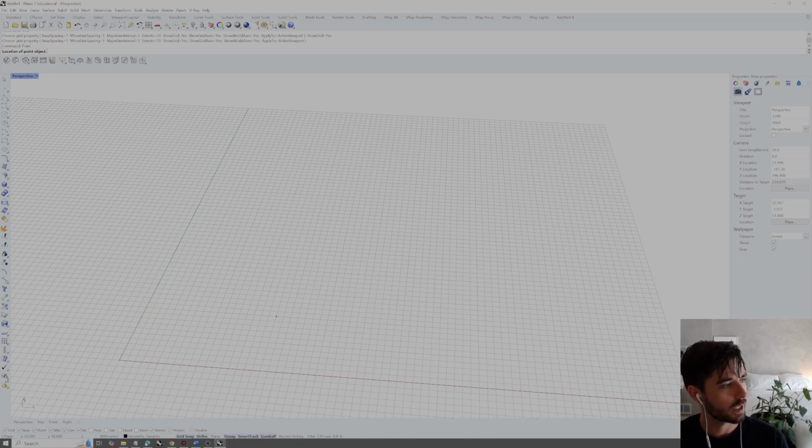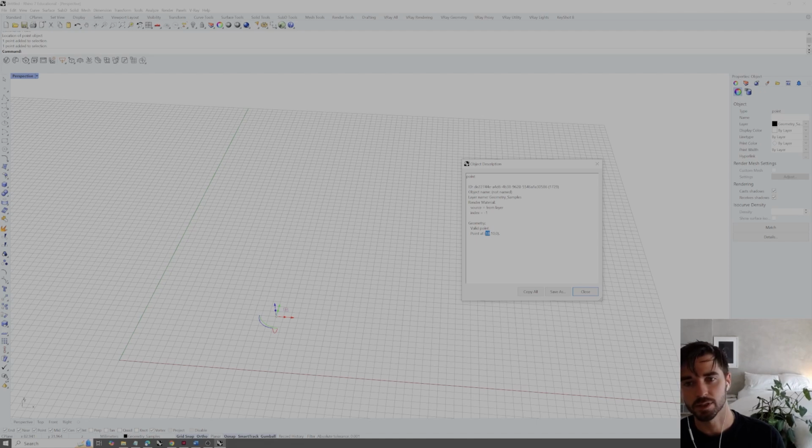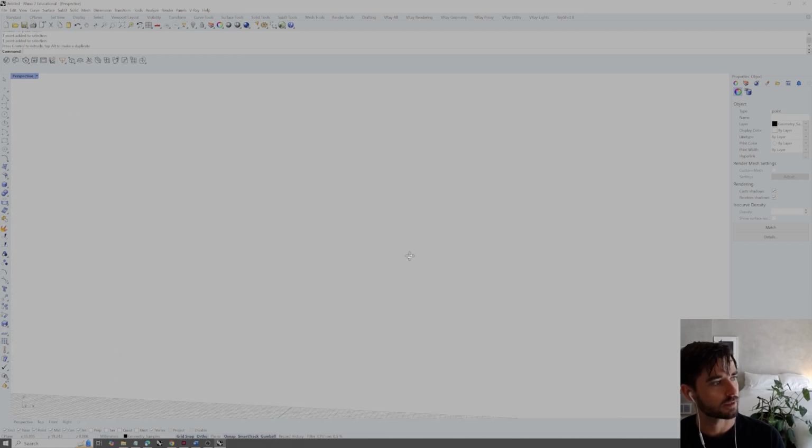So if I now click to deposit that point or construct that point geometry, select that point by left click and dragging across that object, and then go to details, we can see that it's now an integer value of 18, 10, 0. So those are the x, y, and z coordinates of this point. As I move this point up, let me just close this window first. So move this point up, it's still snapping, so we're snapping in the z-axis.